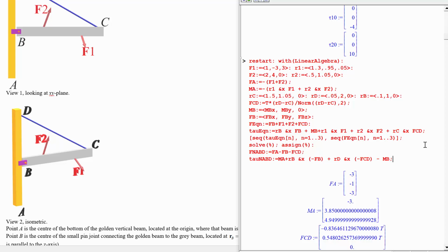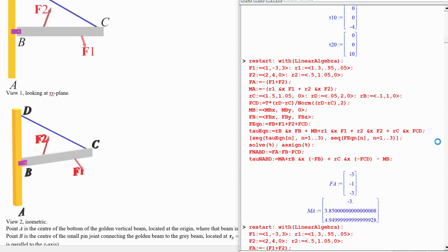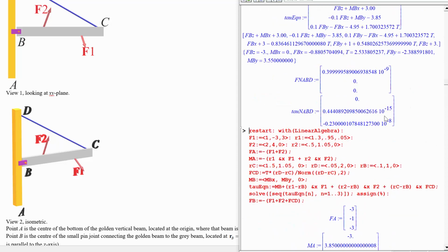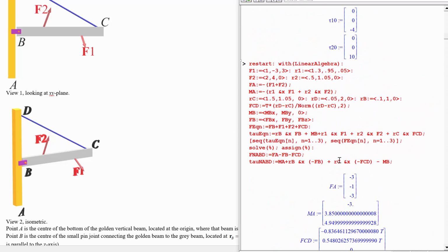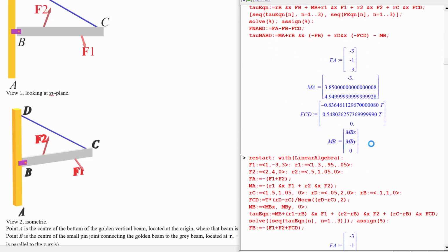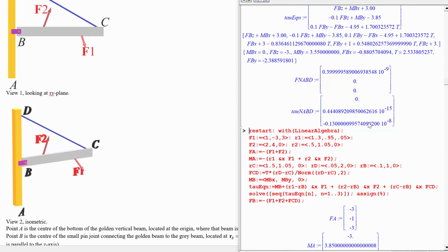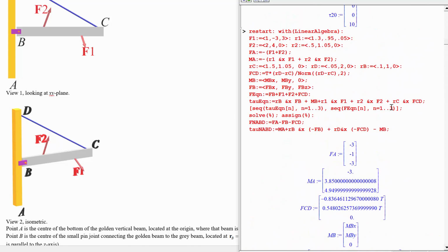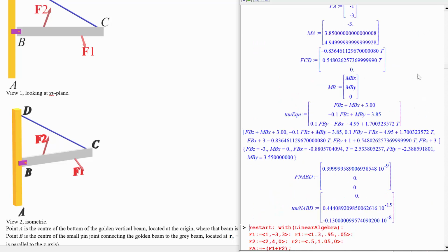Yeah, because the line of action of the force should make no difference between that. So if we use RC, we still get 0. If we use RD, 0 as well. Similarly, up here, when we were finding the torque on BC, we could have used RD because it's along the line of action with that force. And yeah, we found the same torque that way as we found earlier.